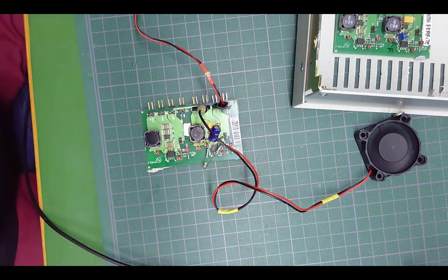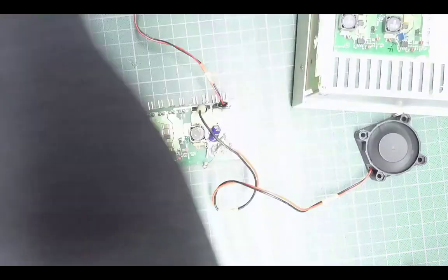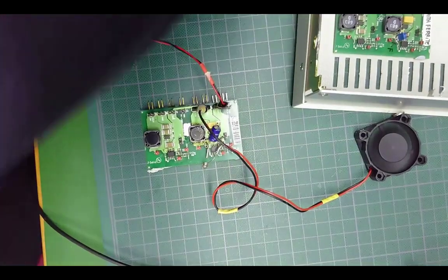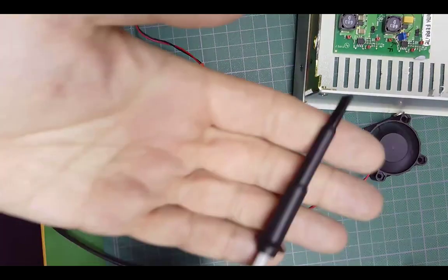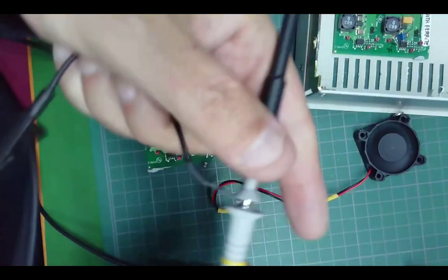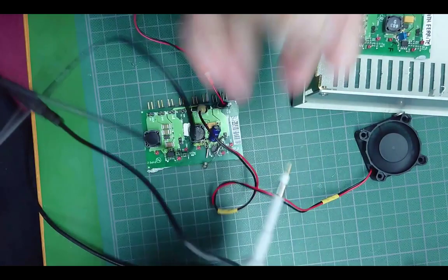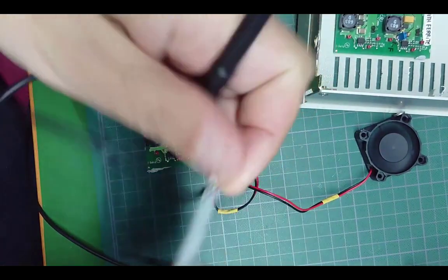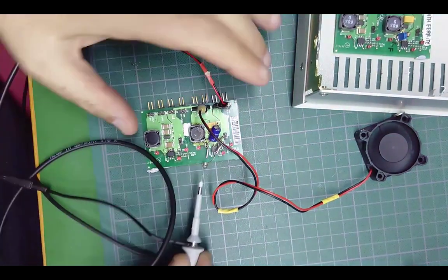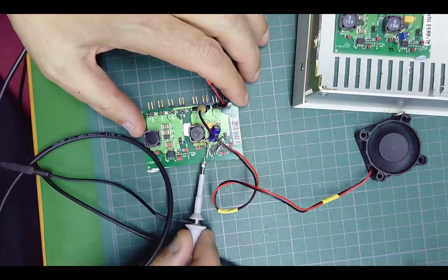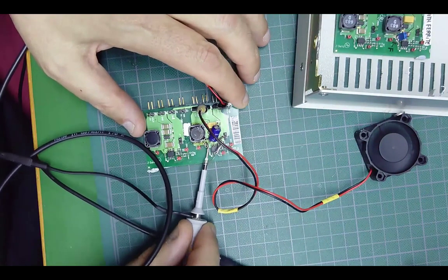So to see how the circuit is switching, I will do the preset of the oscilloscope, and I will connect to channel number 1 a passive probe, okay? Something like this. And obviously, to see how the circuit is switching, I cannot use the pigtail of the probe, so I am going to connect in this way.